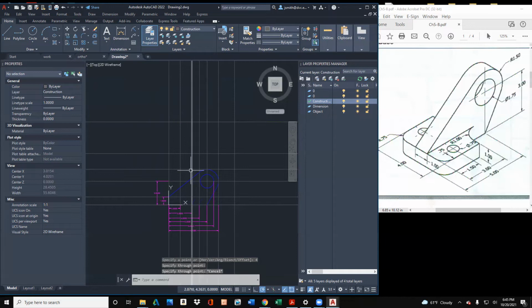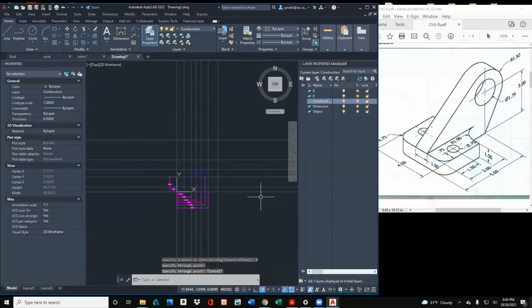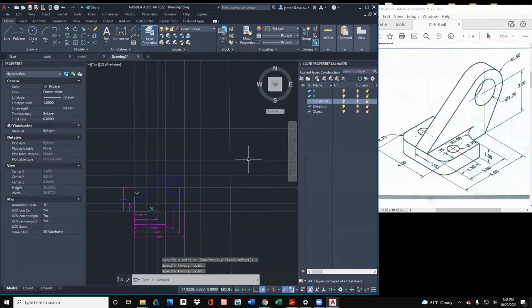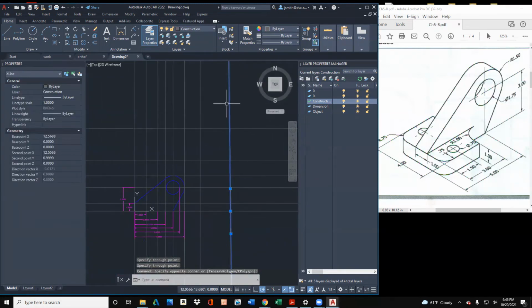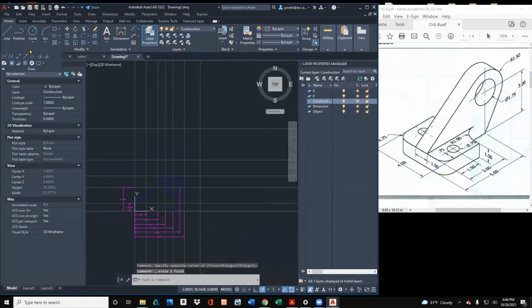That's good. And then remember, whatever width it is on the top view, it's got to be the same from the front or the side view, whatever this corresponding is. So let's do this here. So I'll go here, and I'll type in 4, enter. All right, and then what should happen is I need to slow down and make sure that these are 90 degrees. So let's just, my apologies, let me just slow down.